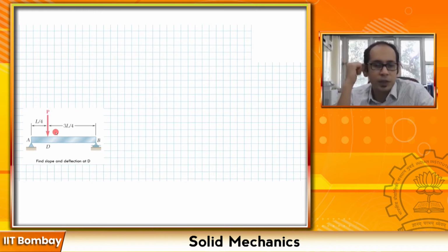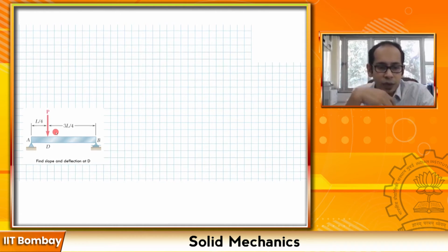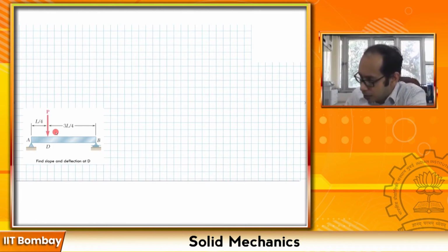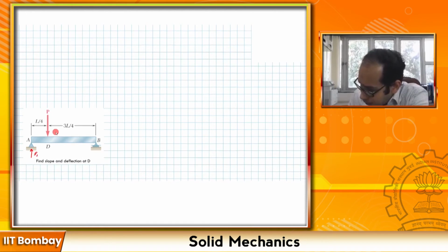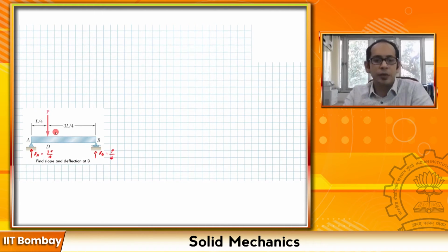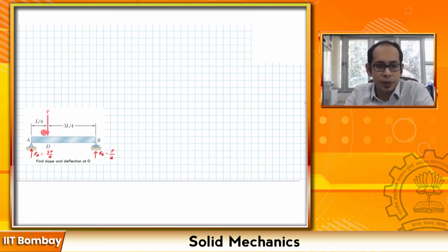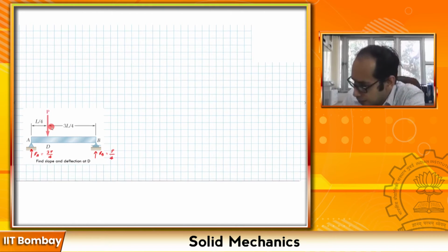So now the question is, how do we solve these kinds of problems where we have a discontinuity of the nature which you have in this expression over here? So let's first go ahead and write the reactions for this one. The reactions are pretty simple. For this beam you have this Ra. These are the reactions, and let's just mark our regions R1 and R2 over here.